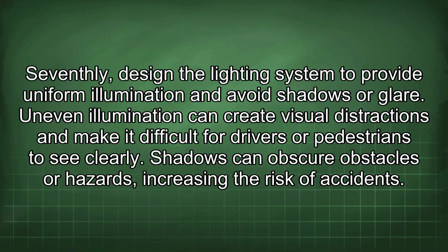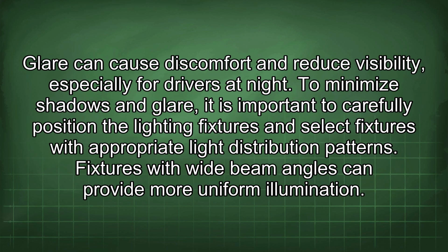Seventhly, design the lighting system to provide uniform illumination and avoid shadows or glare. Uneven illumination can create visual distractions and make it difficult for drivers or pedestrians to see clearly. Shadows can obscure obstacles or hazards, increasing the risk of accidents. Glare can cause discomfort and reduce visibility, especially for drivers at night.